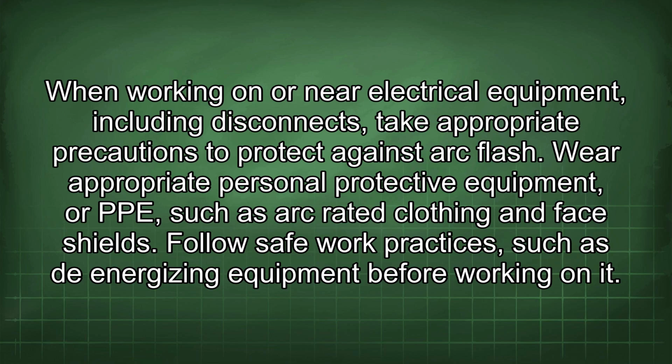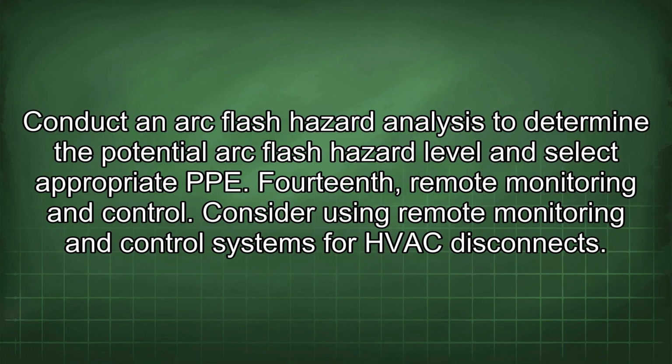Follow safe work practices, such as de-energizing equipment before working on it. Conduct an arc flash hazard analysis to determine the potential arc flash hazard level and select appropriate PPE.